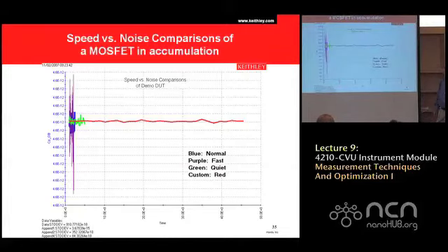So our best standard deviation is about 84 attofarads on a 5 picofarad capacitor. That's 6 digits of resolution on a wafer, on a MOSFET, on a gate. So this is sort of a real world environment that you can experience. This is not some Cal standard that we have plugged on the back of the instrument.